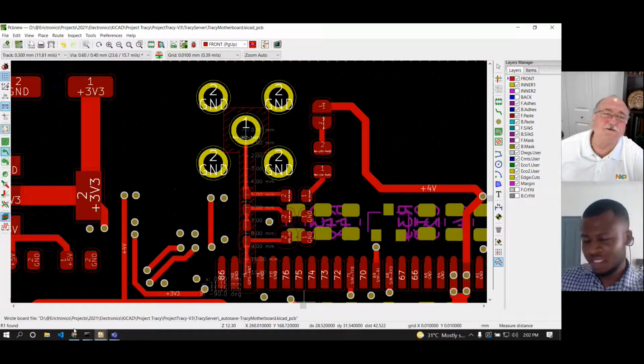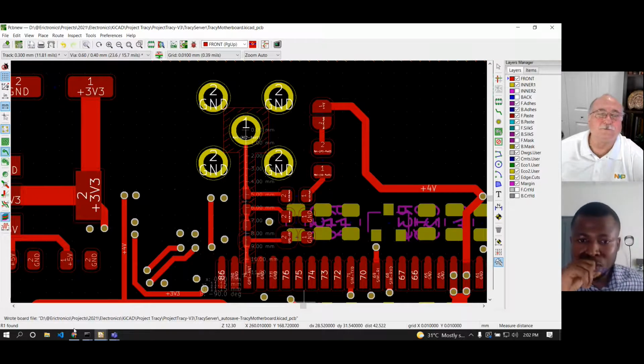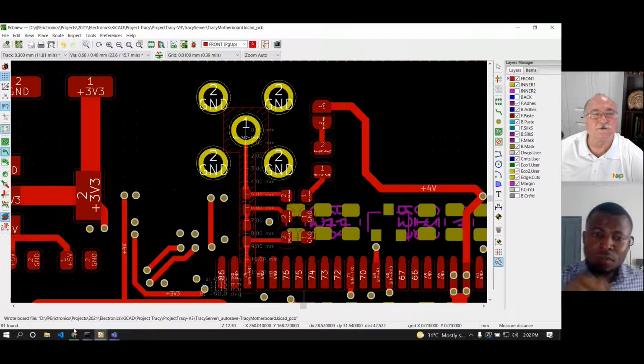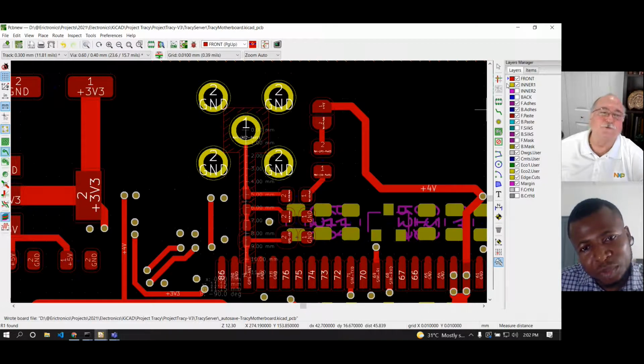The only other thing here is your connector. This is a BNC for the antenna. Look through the board stack and make sure that it's nice and clear between the 4 ground leads and the center conductor for bringing your energy in and out of the board. Straight through the board underneath the connector, you can't route in there, obviously.